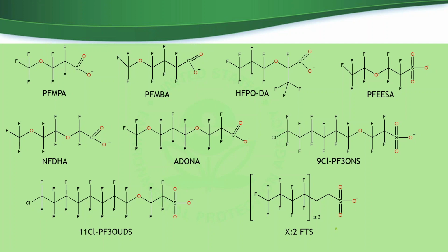Hi, sir. My name is Mike Eller. I am out of EPA Region 3, a leader for an enforcement division sampling team. We've been asked to go out recently and sample some non-drinking water matrices for PFAS compounds using method 537. So two questions for you. One, there's some indication in the very little bit of literature that I've read that certain PFAS compounds partition and sorb to suspended solids in source water. I'm wondering what, if any, work is being done on a method for PFAS in solids. And the second question is, is there any way to source track this stuff, whether through stable isotope, mass spectrometry, or something else? Thanks.